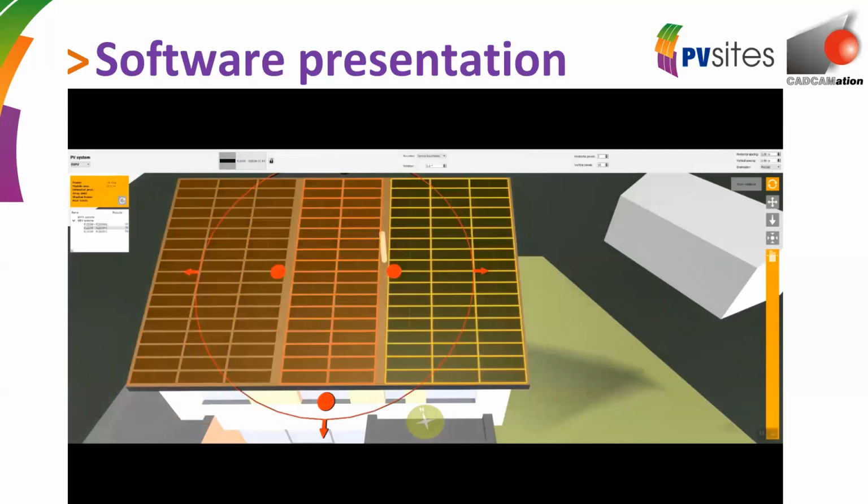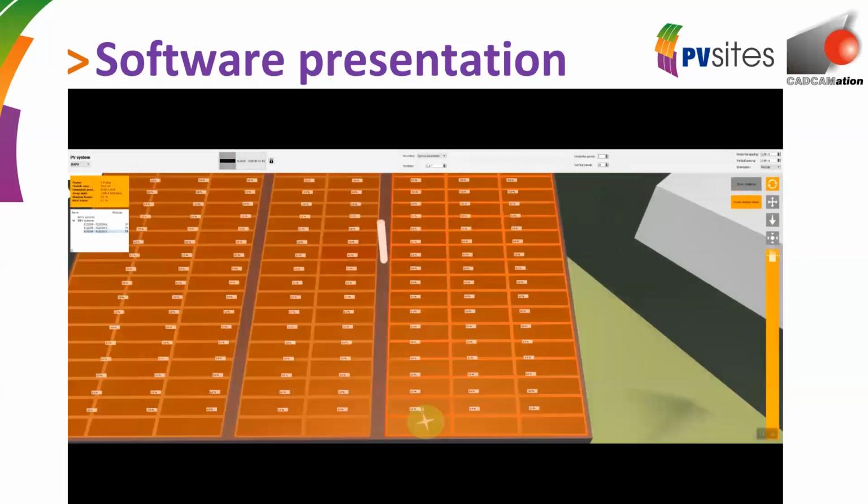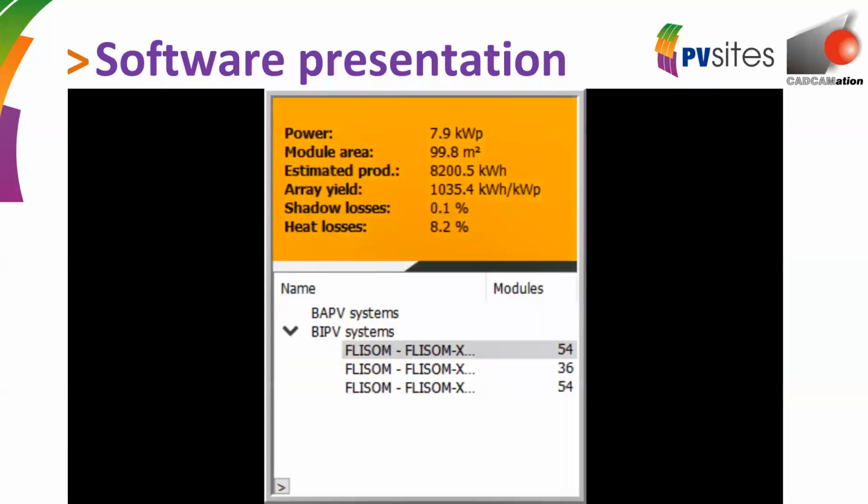So it's very easy to design a roof, and then to get the right number of modules at the right position, and then generate shading effects with simulation, sizing the effects as shading at module level, and you even get the irradiance and the yield at module level.